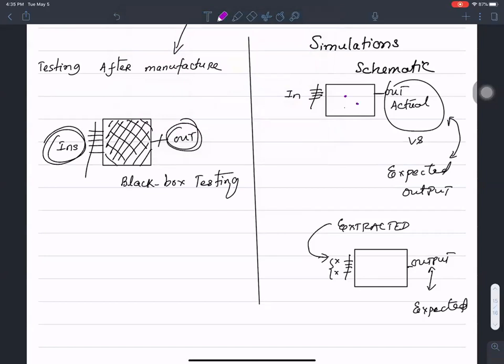On the other hand, when you're doing your software testing, you can annotate the internal node voltages and see the exact voltages at different nodes, the currents flowing through each of these branches. You can analyze the circuit. You can take a look at the internal conditions of the circuit. Not so after manufacture; you cannot put a probe into the internal nodes of an integrated circuit. So you find yourself in a slightly different environment, needing a different skill set that corresponds to black box testing.